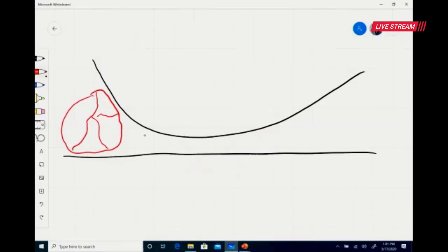Then all of a sudden, we've got a particle that is going to be roughly the same size as that lubricating film, right? And remember, this is somewhere around 1 micron. So something very, very small. It gets in here and it starts to cut, and this is what leads to little debris that looks like crescent moons, or in some cases, it's little curly cues like this. So the wear is caused by the small particles.